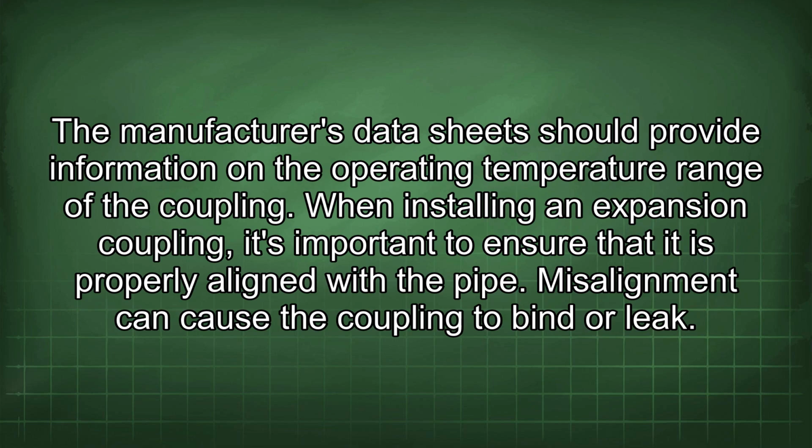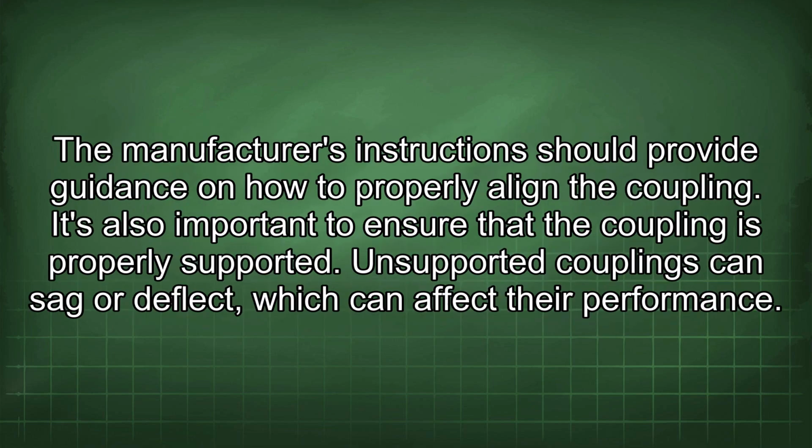When installing an expansion coupling, it's important to ensure that it is properly aligned with the pipe. Misalignment can cause the coupling to bind or leak. The manufacturer's instructions should provide guidance on how to properly align the coupling.